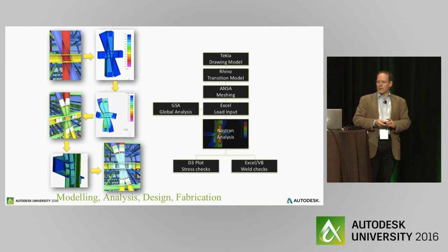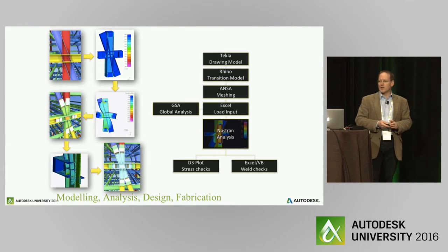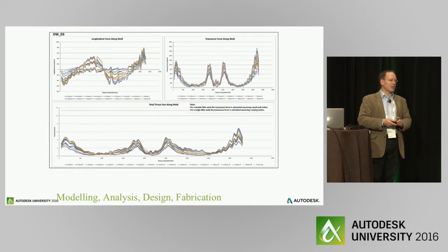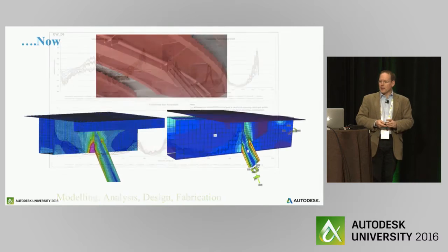So we still use a lot of this methodology, but what we've got out of this tool is a much quicker, simpler way to analyze the likes of a node like that. We were also able to create weld plots, looking at different load cases. But this tool, the StatiCa connection tool, is able to produce all of this in one output and very quickly as well.